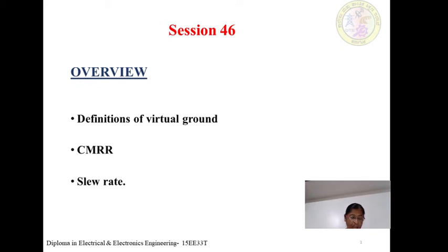the output is not amplified, because the differential amplifier amplifies the difference between the two signals, that is V1 minus V2. For common mode signals, this difference is 0. Hence, for common mode operation, V1 is equal to V2. So we won't get an amplified output at the output terminals of the differential amplifier. Let us now see what is meant by differential mode signals.